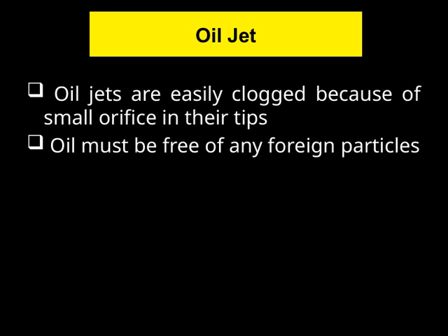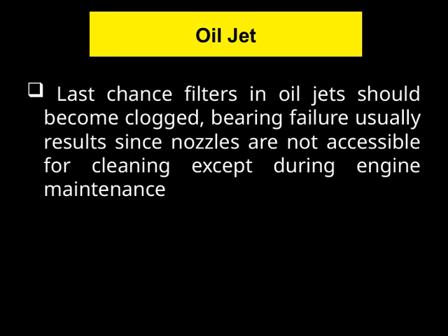Last chance filters in oil jets are critical components, but they can become clogged over time. When that happens, it often leads to bearing failure, which can be quite serious. The tricky part is that nozzles are not easily accessible for cleaning, except during scheduled engine maintenance.